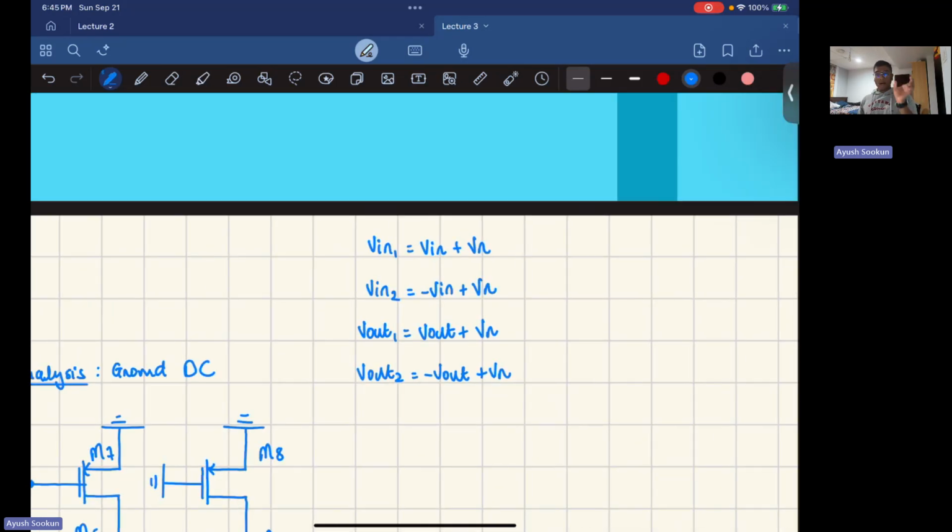Now you might be saying, why do I have only the V input 180 degrees phase shifted and not the noise? Well, the input I'm giving into the circuit, I'm choosing. I'm saying, hey, this one is the same, but the other one, V in 2, is going to be a 180 degrees phase shift of the first one. I'm doing this by choice, because this is the best way I can do it. The noise, I have no choice over that. It's whatever wires I have in the building I'm working with. So I don't have control over that, so I can just put it as noise. So I have plus noise, or minus noise. However, since we chose plus, we have to be consistent every time we add the noise, so our math is correct. You could say minus noise, for sure, that's up to you. But I chose plus because I don't like to deal with minus signs. I always make a mistake.